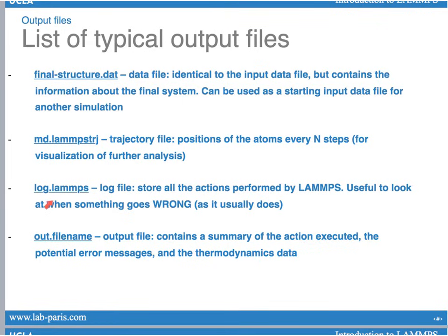Then you always have a log file that is created, log.lammps. This file typically contains everything. LAMMPS will store in this file all the information about what it is doing and a lot of information about the simulation itself. Typically, this is a file that is useful to look at when something goes wrong.